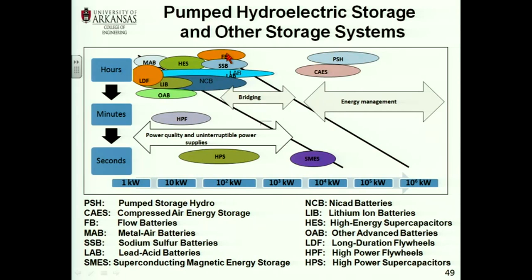That was the internal impedance of your infinite bus, to account for the fact that you don't have an ideal voltage source, that there is a voltage drop as the current increases. Well, a battery, the simplest model is a DC source with a resistor. And so what happens? When I'm charging that DC source, I'm going to lose power on that resistor. When I'm discharging that, I'm losing power on that resistor. So that's the reason why we talk about the return efficiency.